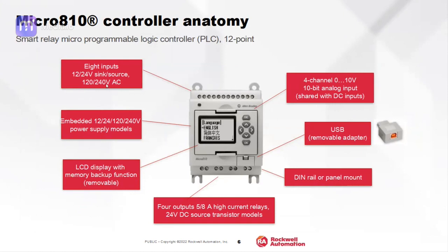This input is available in different variants, 12 volt DC, 24 volt DC, and then 120 volt or 230 volt AC is available on the input side. On the auxiliary supply side, if it is 12 volt, input is 12 volt available, 24 volt is available, 110 as well as 230 volt auxiliary power supply is available with this hardware. Different power supply modules, if our control voltage required is 110, we need to go with 110-volt auxiliary supply.